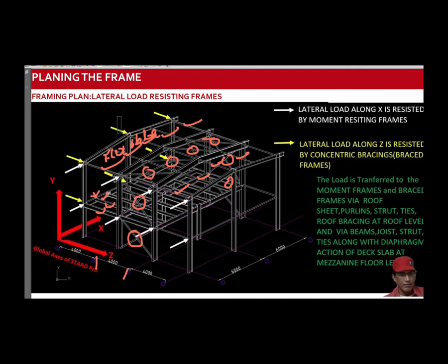A semi-rigid diaphragm is nothing but the actual stiffness of a deck slab in lateral direction. A rigid diaphragm is something which is entirely rigid. It has a rigid body movement. It moves like a rigid body; the whole of the system will move.